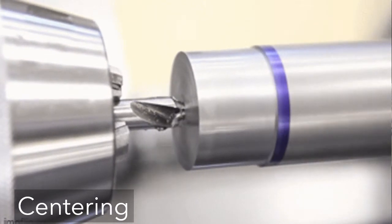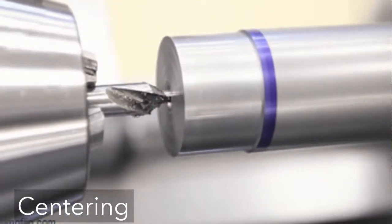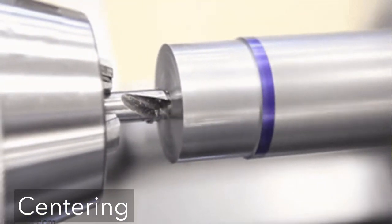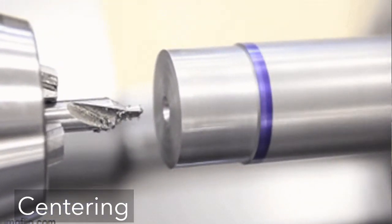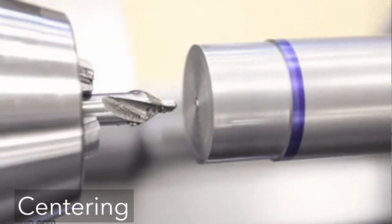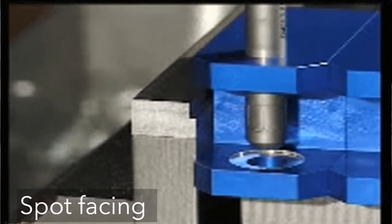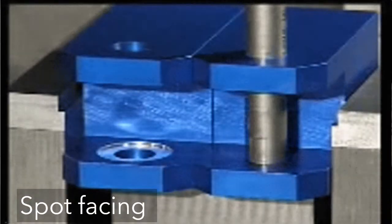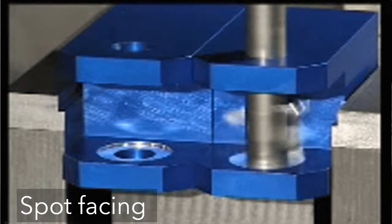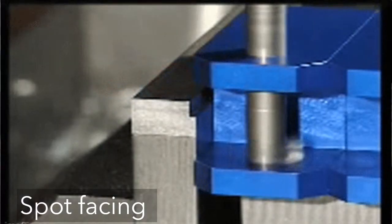Centering, also called center drilling, is an operation to drill a starting hole to accurately establish its location for subsequent drilling. The tool is called a center drill. Spot facing is similar to milling. It's used to provide a flat machined surface on the work part in a localized area.